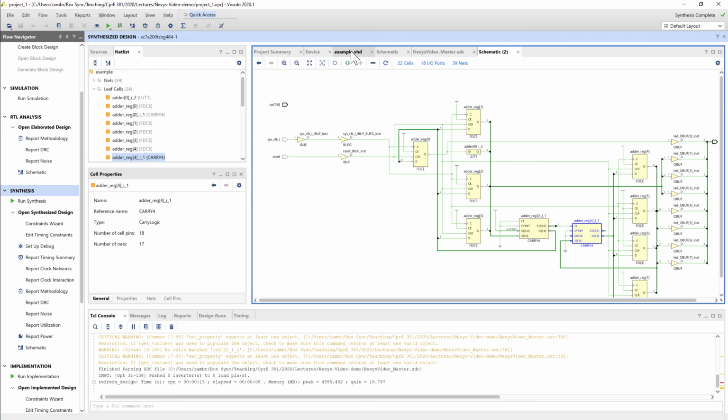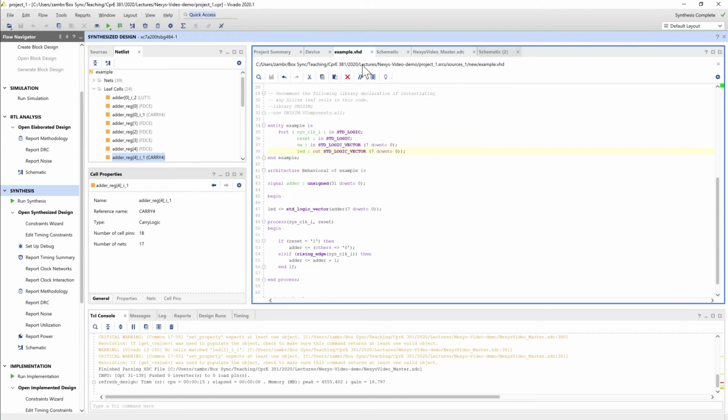But Vivado, any FPGA synthesis tool, is going to be extremely aggressive in this, which you can call dead code elimination. It's also referred to as observability analysis. If that signal that you're using is never going to be seen anywhere, if it doesn't correspond to a physical thing in the real world or any output pin, basically, get rid of it.